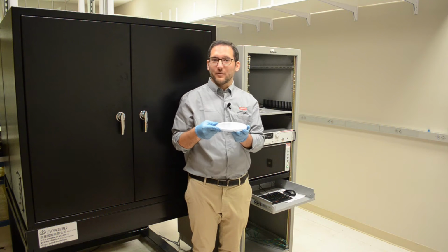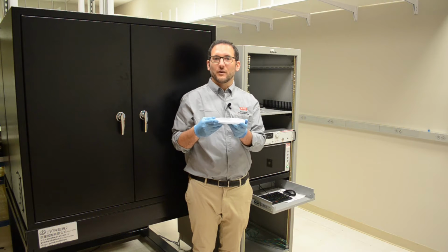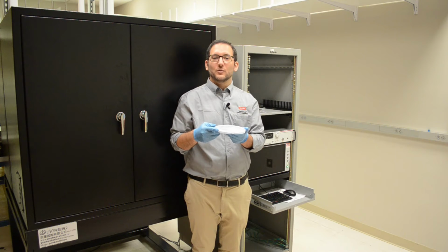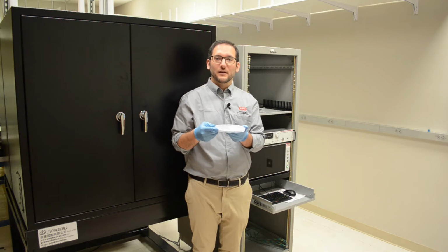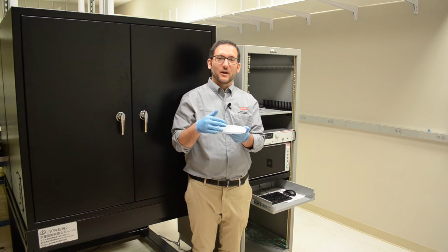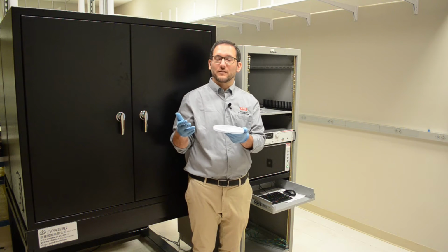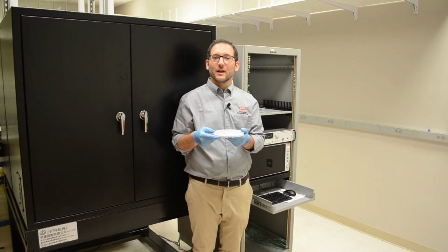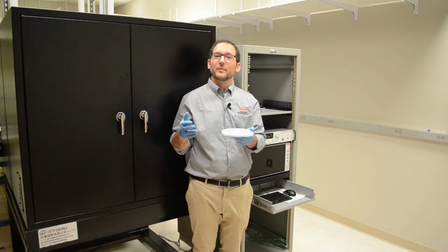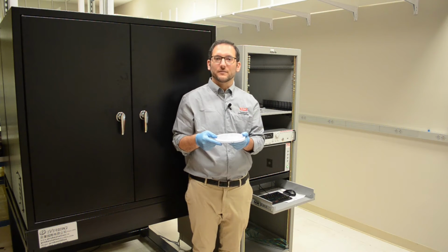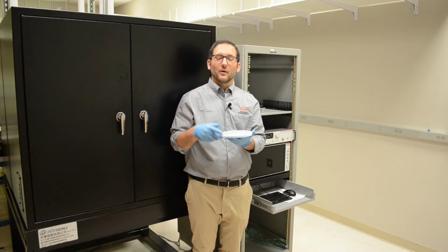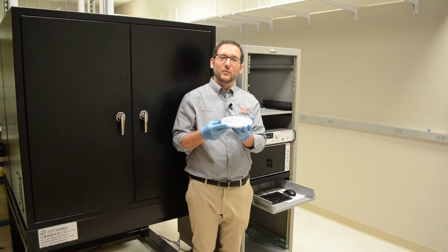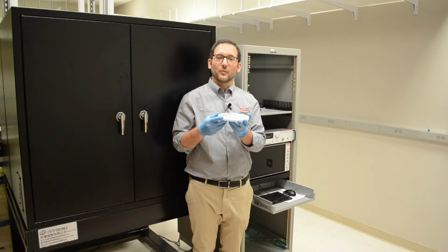After we complete fabrication, and during the fabrication itself, we have to perform electrical characterization. This allows us to assess the quality of the materials and the quality of the fabrication steps as the process is executed. So usually, a fabricated wafer will consist of not only finished devices like transistors and diodes, but will also consist of test structures that allow us to isolate problems that we might be observing in larger devices. So the question that I'll be trying to answer today through this demonstration is how can we test these types of devices when they're on wafer?